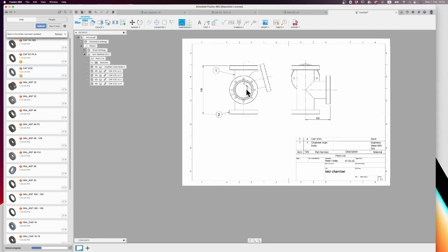And then we're gonna need to communicate the angle here, so 75 degrees or 105 degrees, so whatever you wanna do, 75 degrees. This has a certain offset from some reference. In this case, I'm going to reference the bottom. That's 123 millimeters.